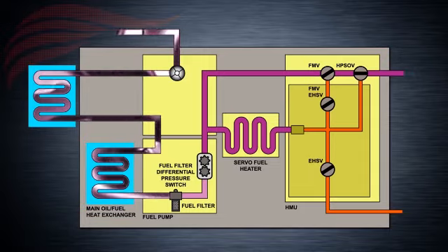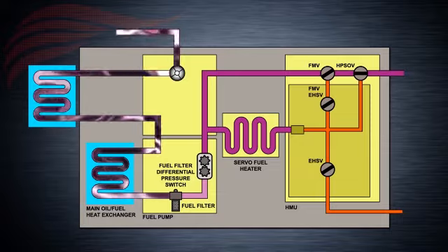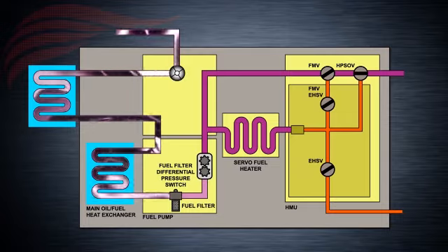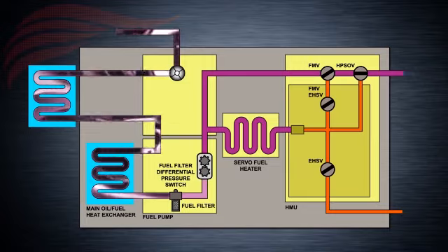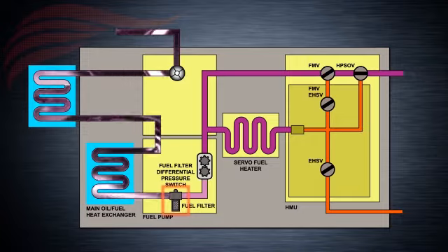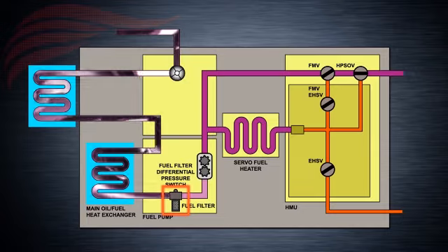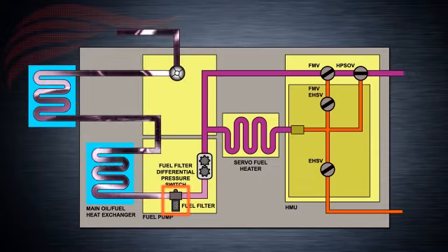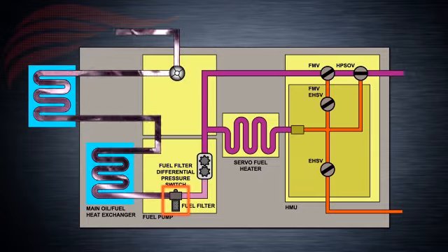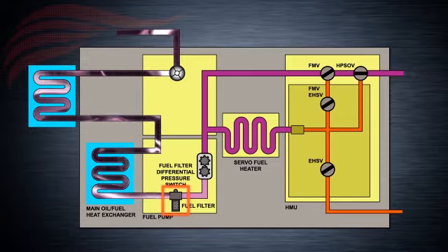Now, time for filtering. Any form of fuel contamination is bad. It makes combustion difficult and subsequently decreases the engine life. In some cases, when the fuel is excessively contaminated, it may even lead to an immediate engine failure. To prevent this, fuel is filtered to minimize the presence of contaminants. If contamination clogs the filter, a bypass valve opens and fuel does not go through the filter before it continues towards the engine, ensuring that fuel flow is not sacrificed. It's better to have contaminated fuel temporarily than no fuel at all.